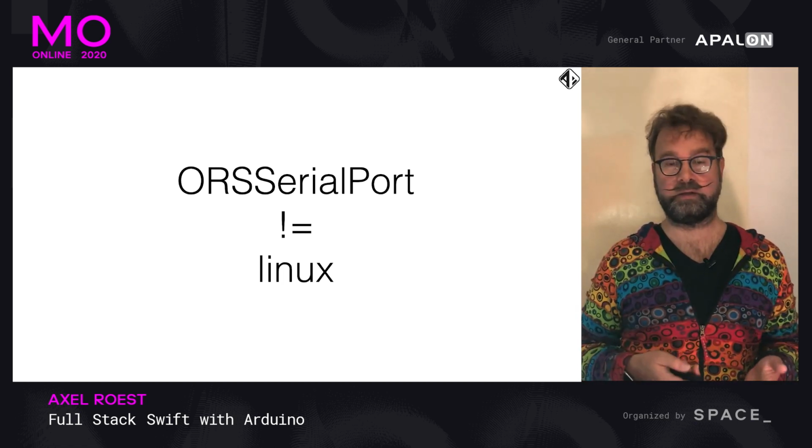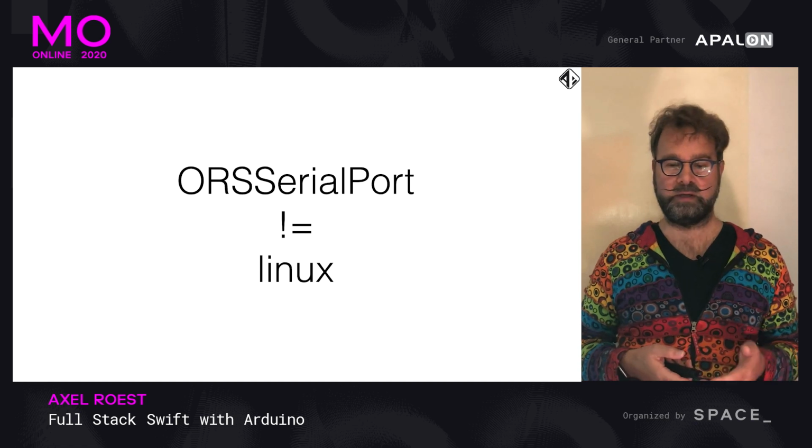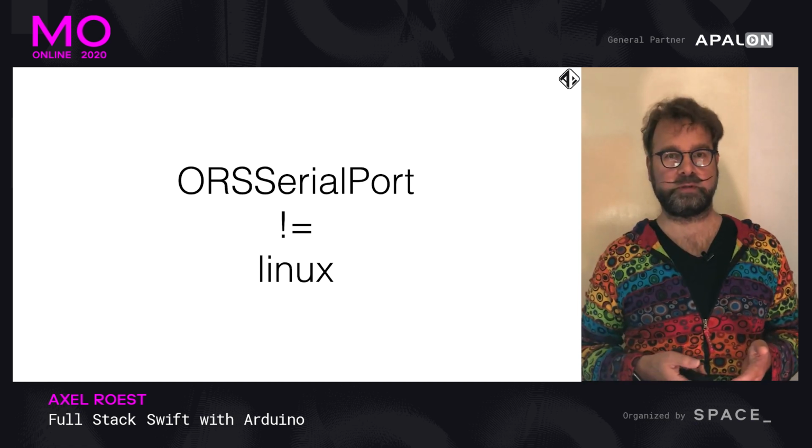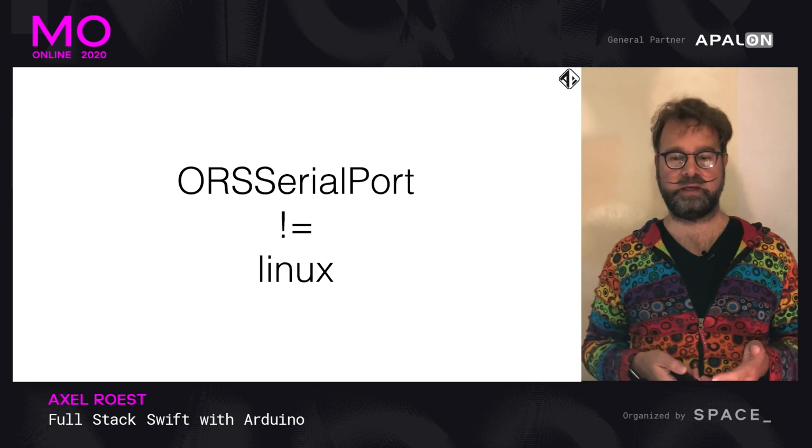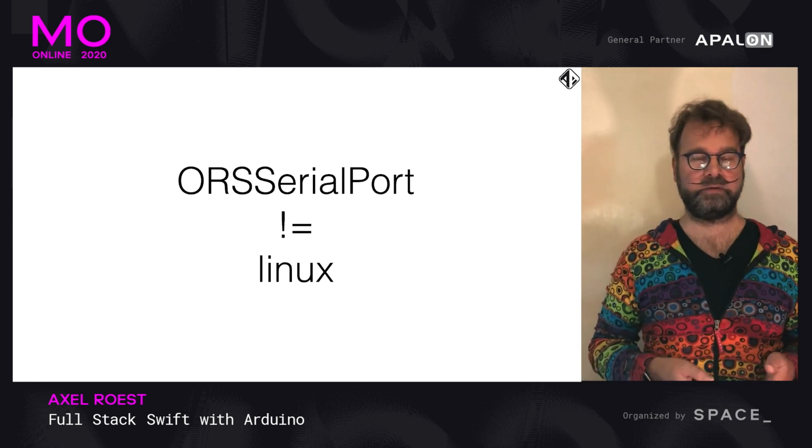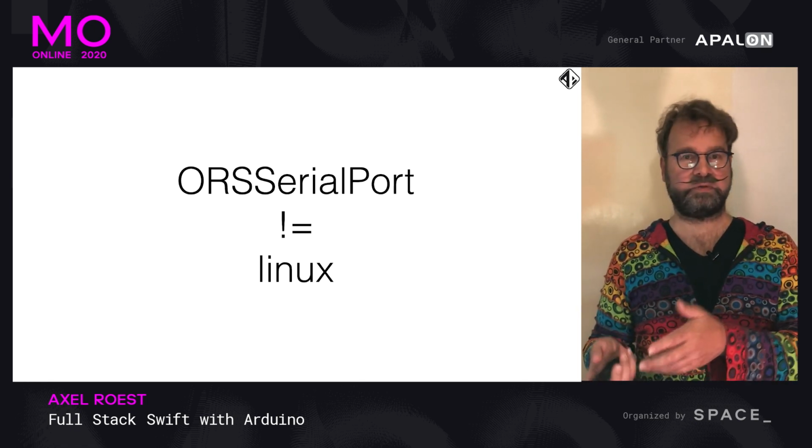So I found another library, which is called SwiftSerial, to connect to the serial port, but that had issues with multi-threading and baud rate problems. You set it to a certain baud rate and then it would default to another one.